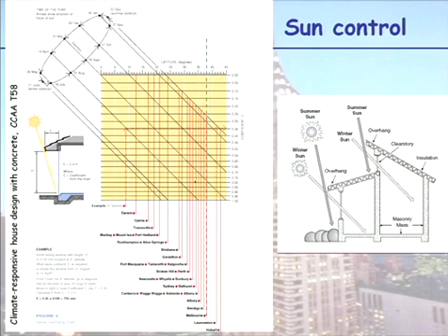In this graph here, these are all different places in Australia. This here is the coefficient C, which is the ratio of your horizontal awning E to your window height H. So C is equal to E on H.